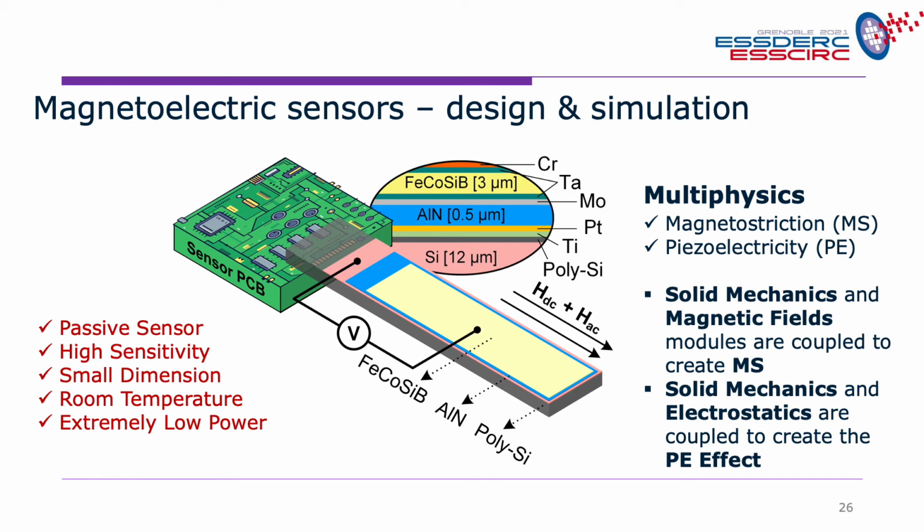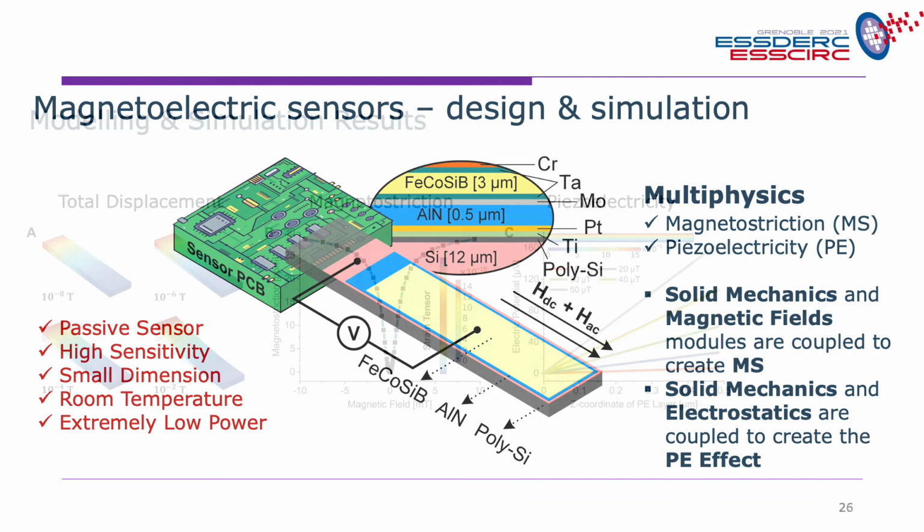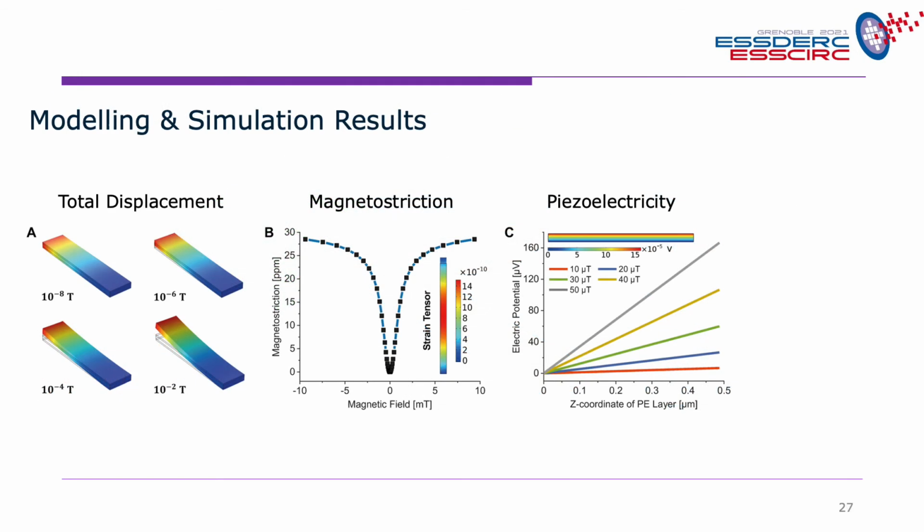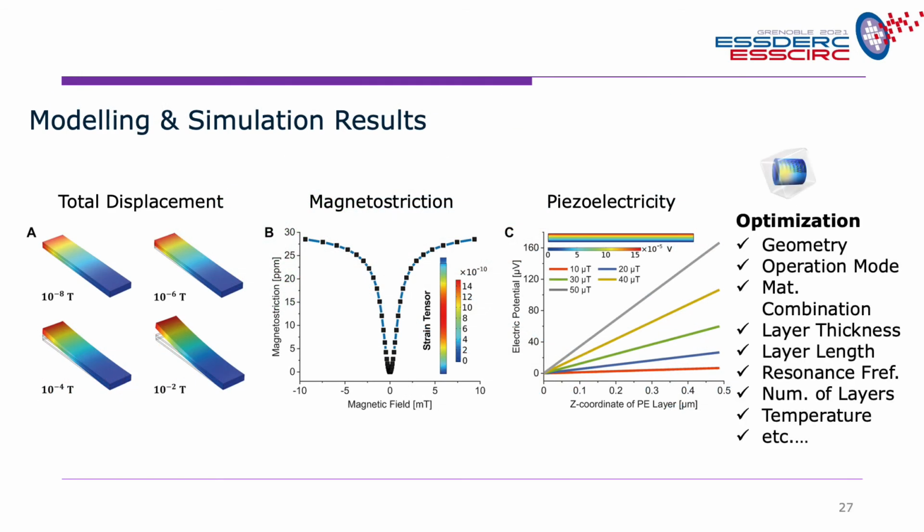So this is the magnetoelectric concept that, as you can see here, the dimensions also exist. We ran simulations using the finite element method with COMSOL, covering the total displacement, magnetostriction, and piezoelectricity. We have done all of them for the detection of the few picotesla that is required.